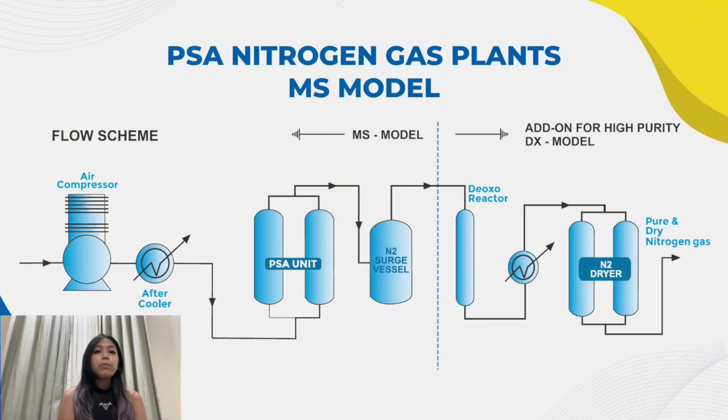So, for the first manufacturing process, I'm here to introduce the pressure swing adsorption for nitrogen. So what is pressure swing adsorption? Pressure swing adsorption is a technology used to separate some specific gases from a mixture of gases under pressure according to the species, molecular characteristics, and affinity for an adsorbent material. It operates at near ambient temperatures and differs significantly from cryogenic distillation techniques of gas separation.